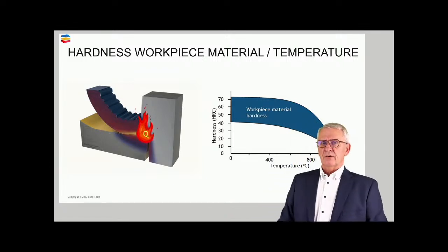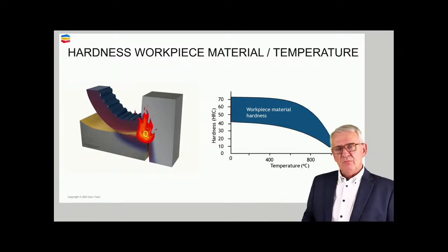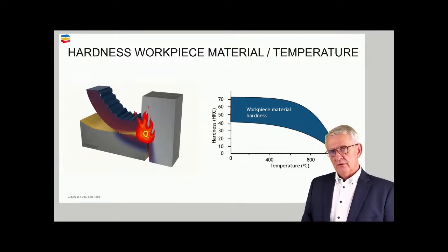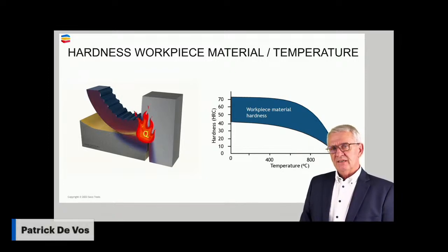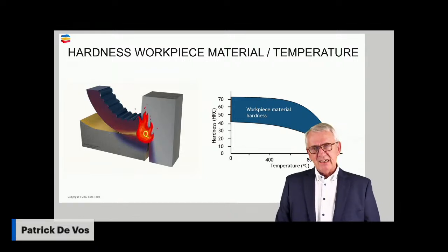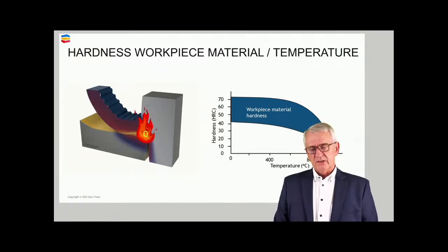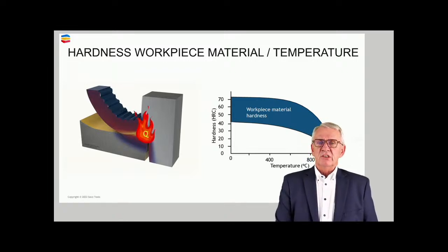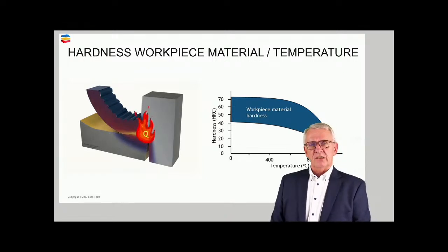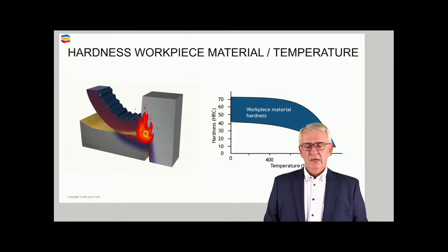And that's what I try to show in the diagram here. If you have materials with hardnesses which are at room temperature rather high, if we heat them up so the temperature becomes around 700, 800, 900 degrees Celsius, the material softens. And in machining, this is perhaps the secret of hard turning, hard machining in general: if I can make sure that just before the material is being cut, the temperature there is so high that the material softens to a level that makes it easier to cut, hard turning is not a big problem. It becomes soft turning at higher temperatures. And that is the whole secret.